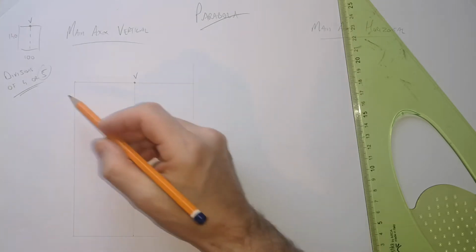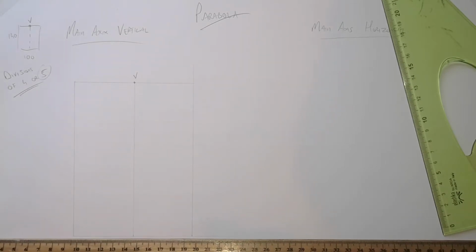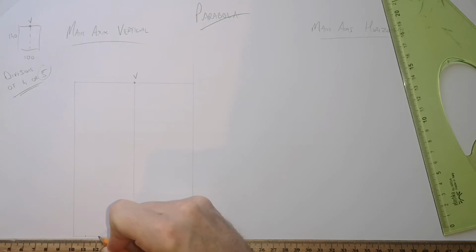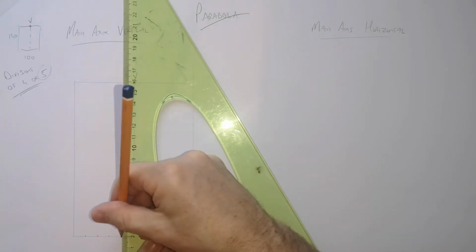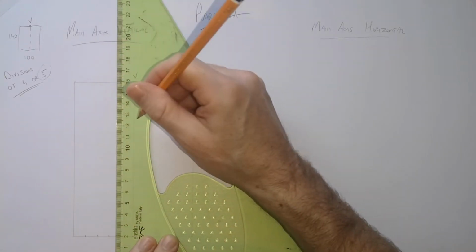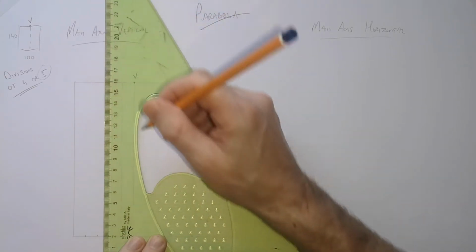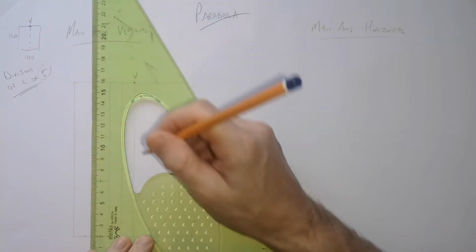Much easier. So 5 divisions, well that is 50 mil across. We just slide this so you can see it. So 5 divisions is actually quite easy. 10 mil each time. There we go. And these lines are going to be drawn parallel to the main axis. Now these are all light construction lines. They should be a little bit lighter again in your drawing. I'm just going a bit dark so you can see them.